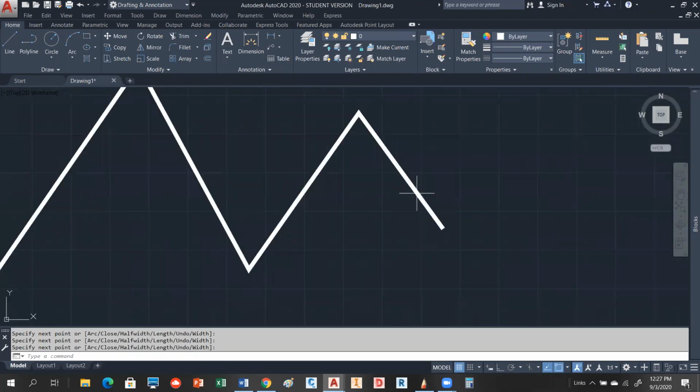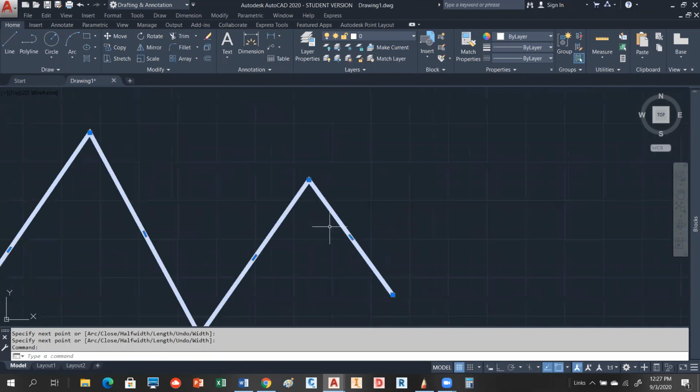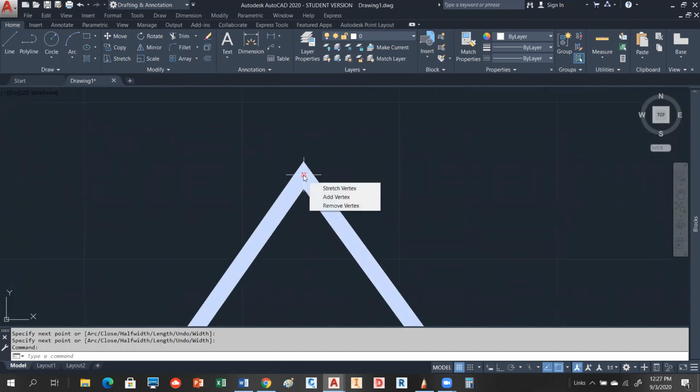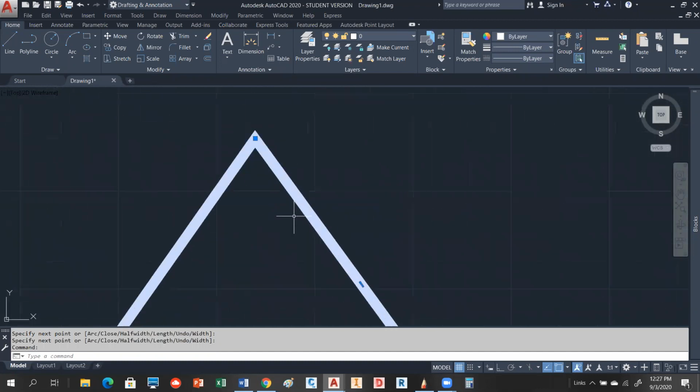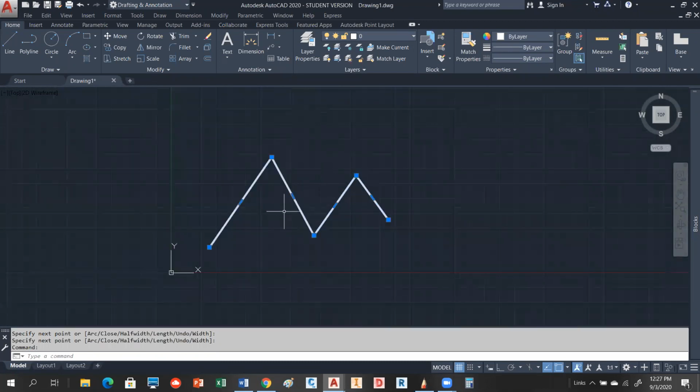Yeah. So if you would click on your polyline, and we saw this with the rectangle last week, you'll notice that this is embedded right in the center there. That one is embedded right in the center. So that's how that works. And the edge of the polyline really doesn't exist, okay? It's just the way it looks, okay? So if you just select it like that, you can hit the escape key. That'll terminate it, okay? So that one's a pretty straightforward process.